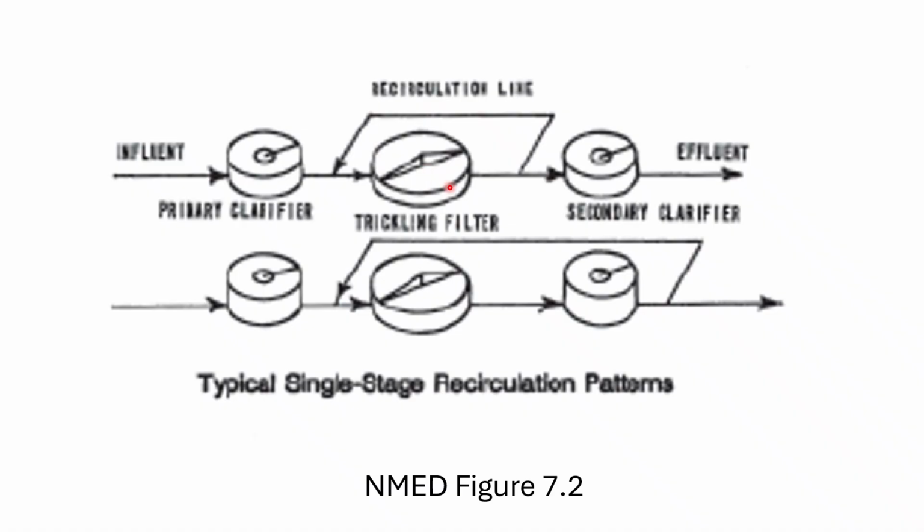They're going to metabolize it, and it's going to go down to the under drain assembly, and then we can recirculate and send it back to the head here, and we can have another pass here before it goes to the secondary clarifier, okay? And in the secondary clarifier, we are going to allow the microbes floating around in the effluent to metabolize that organic load as well, and then it heads out as effluent, okay?